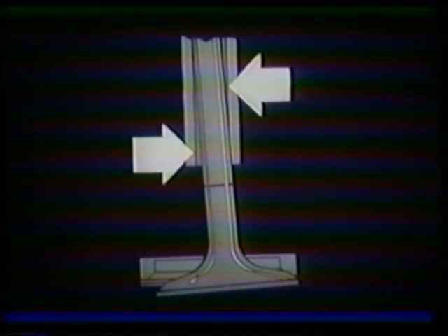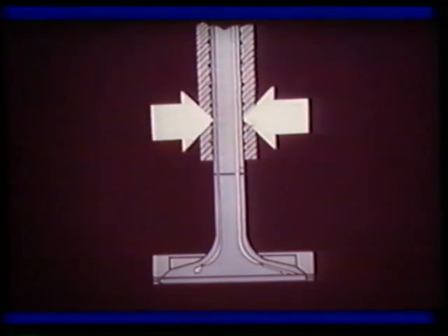Such a condition subjects the valve to high point loads and could fracture the valve. It doesn't take too much imagination to visualize the potential results of this type failure. Too little clearance prevents the formation of the essential film of oil. Without efficient lubrication, the valve will seize.